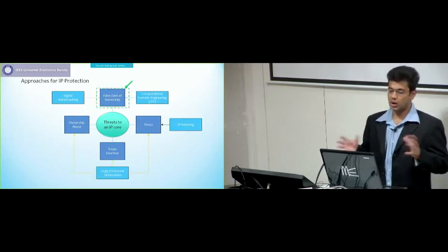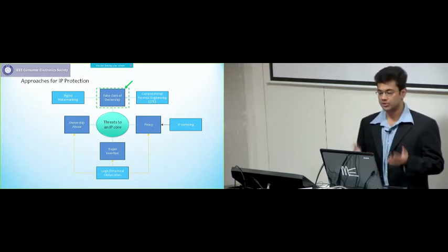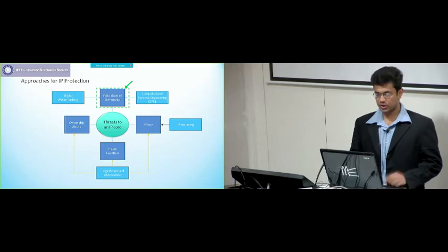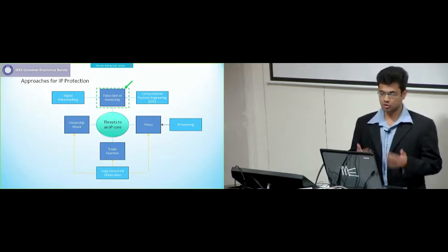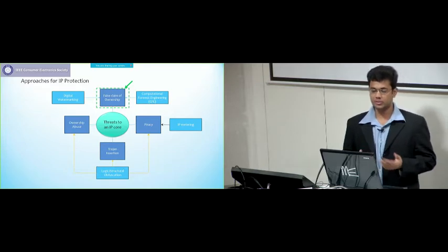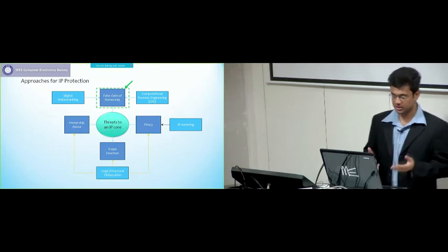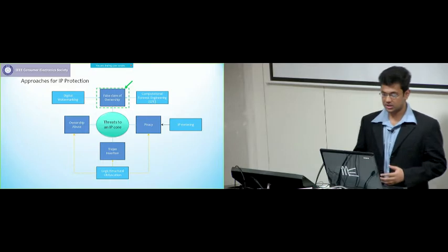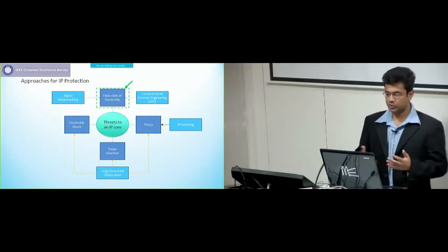The mechanisms to counter or protect against this are digital watermarking, computational forensic engineering, IP metering, logic or structural obfuscation, and a few others. What I would do today is focus on digital watermarking to show how an anti-piracy aware chipset could be made, and also give you a detailed analysis of computational forensic engineering, as these two methods are widely acknowledged and extremely popular in tackling this problem. The way we do it, I'm going to present.